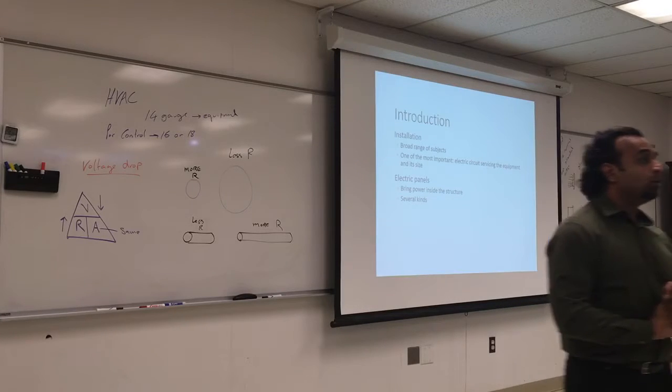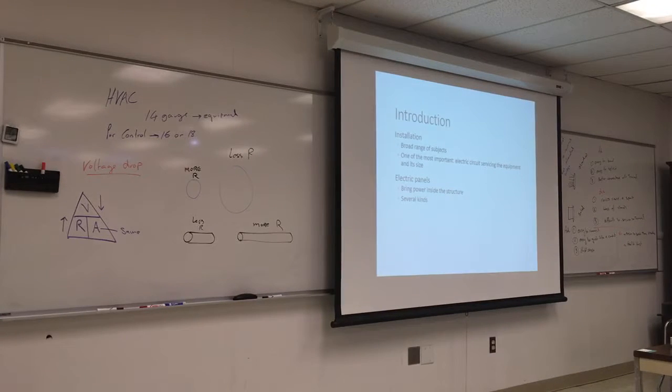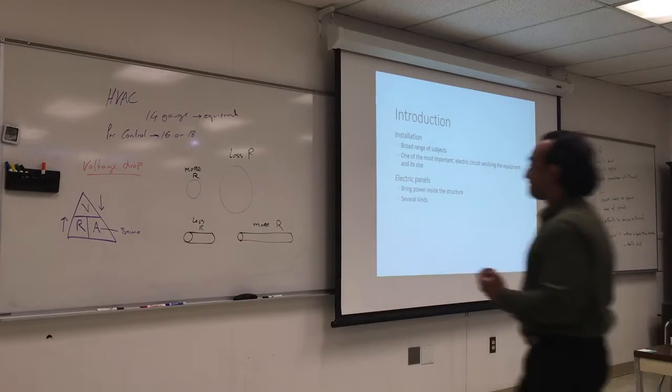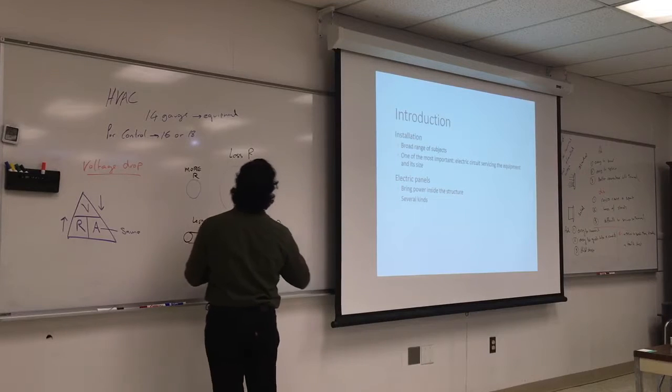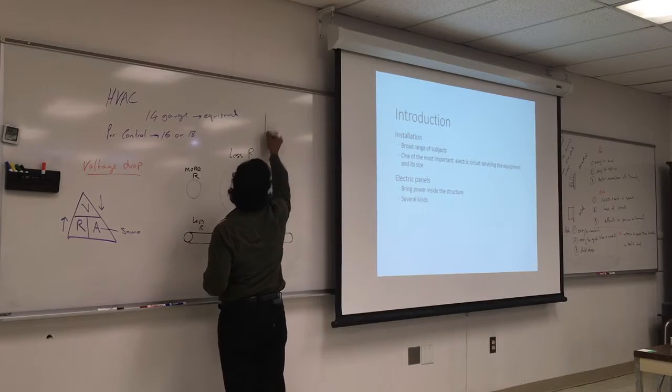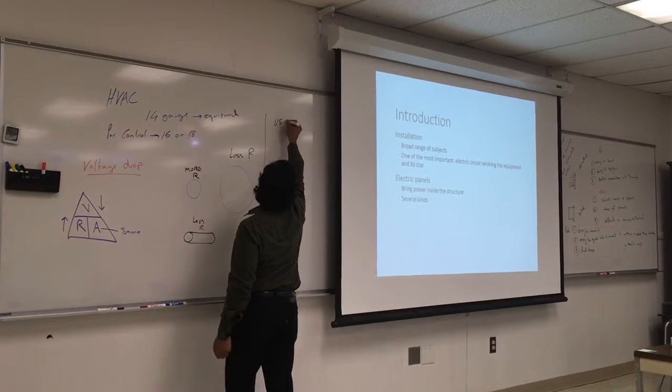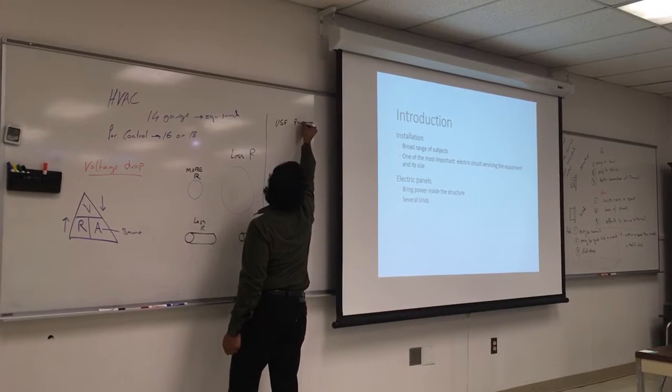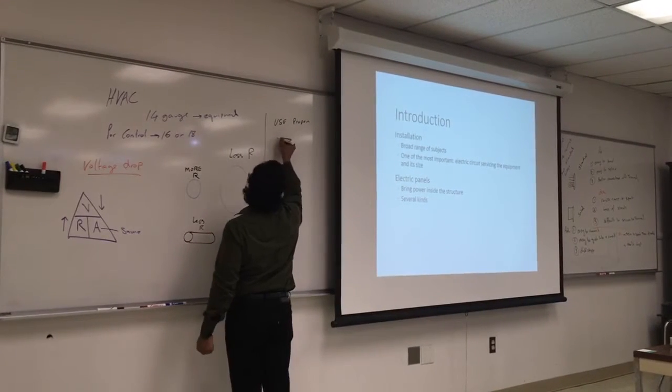If you have noticed from the small connection we did, it's always good to have the right connection and the right equipment. What do we use? Spade connectors. Those are really convenient, make things much easier. Instead of trying to put the wire in the terminal, where it's not secure, you put it in a flimsy way and it comes out. It gets really frustrating. So you want to use the proper connector.